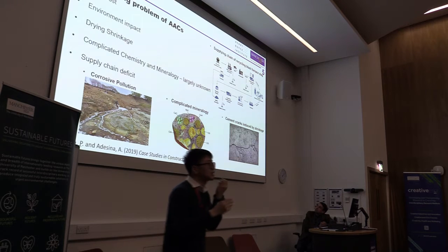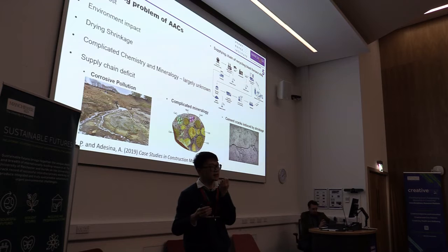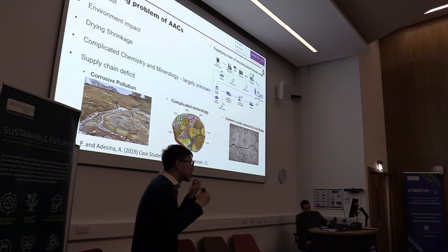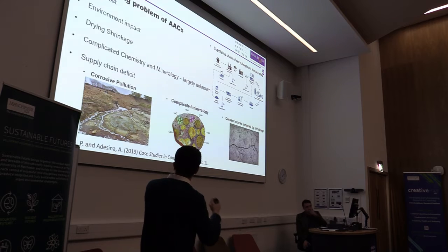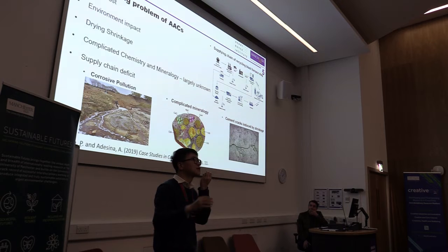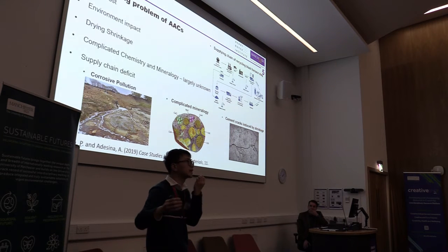High cost, especially for sodium silicate and sodium hydroxide activated cement, because the activator is a strong alkaline solution and is very expensive. The second limitation is the environmental impact, because sodium silicate and sodium hydroxide are both strongly alkaline.